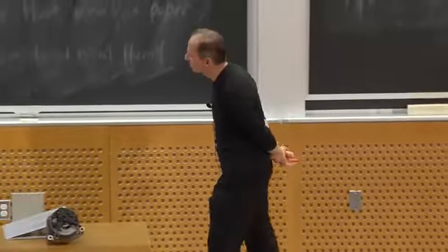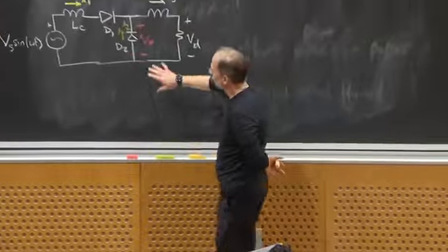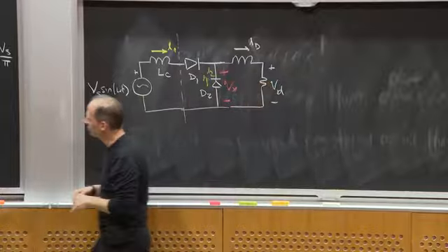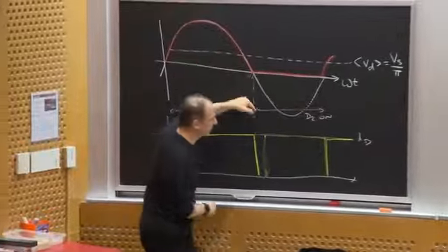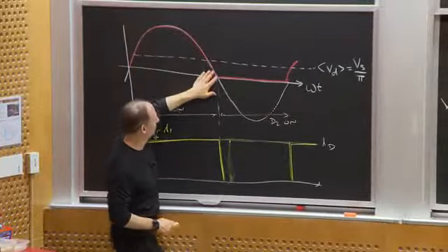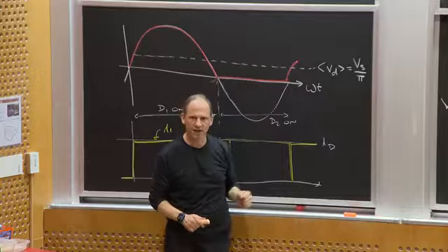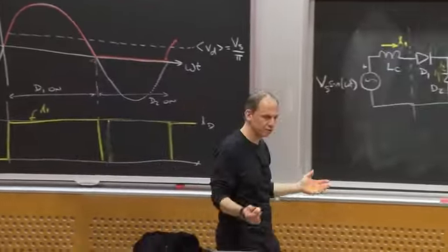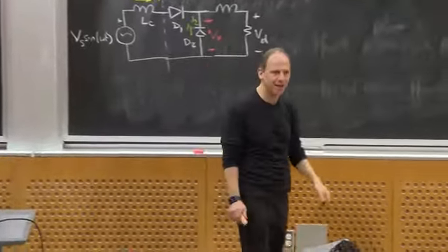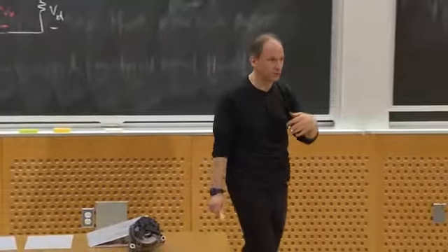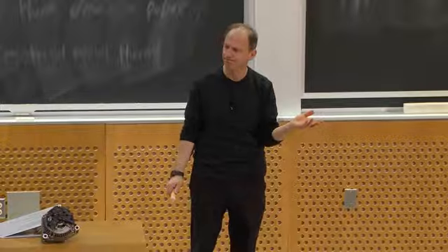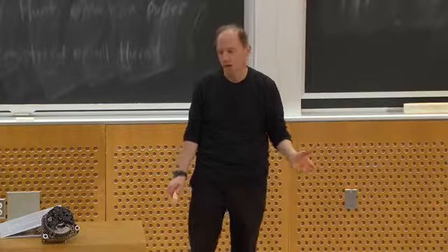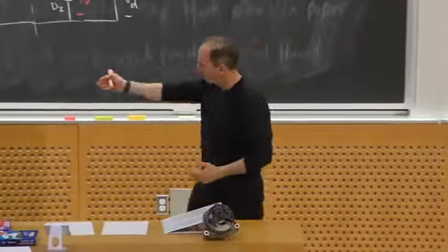And the answer is because this often happens, right? Where do we see, I mean, from here on, what I have is a rectifier, right? We saw that, basically I took a perfectly AC voltage and then I turned it into something with a DC component, I filtered and I extracted the DC, okay? Well, we do that all the time in all kinds of things, right? If you're plugging your laptop adapter into the wall, at the front end of that thing is a rectifier, which is converting AC to DC. All kinds of other applications have that. In fact, it's true for the wall.